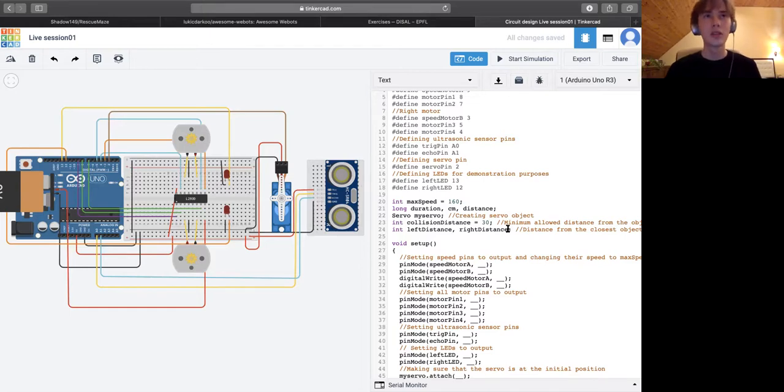Well, it mainly depends on how much accuracy you want. If we analyze the real setting, as you construct the real robot, it usually isn't so much accuracy. For example, at least in my code, for the forward function, I had to change the maximum speed of one side and add 10 to it, since it was shifting a bit to the right.